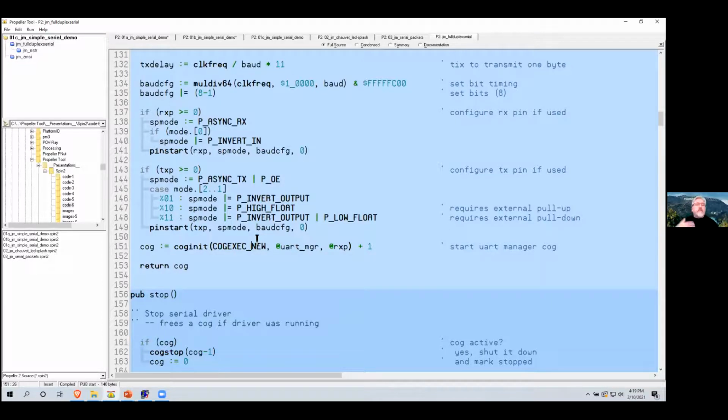In the P1, though, there was a lot of work going on because if you look at full duplex serial in the P1, it will make your head go a little fuzzy for a bit because it's doing what Chip calls ping pong multitasking, where it's divided up the transmission and the reception into small chunks of code, and then it's bipping back and forth between them.